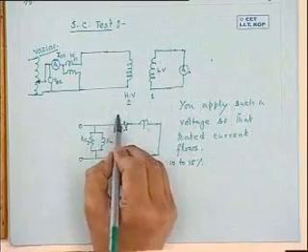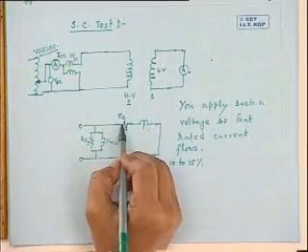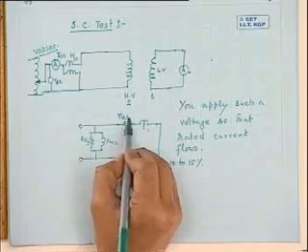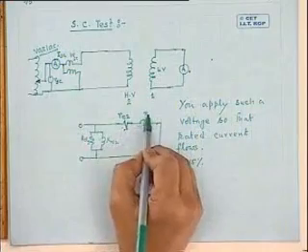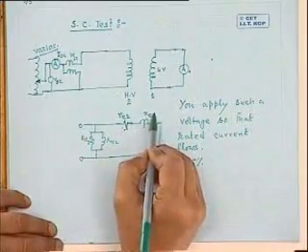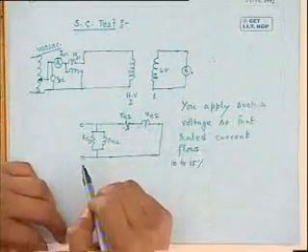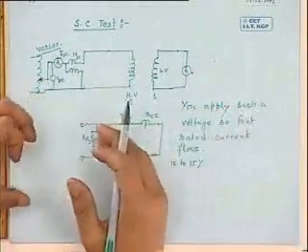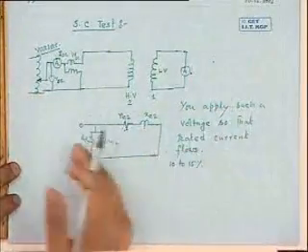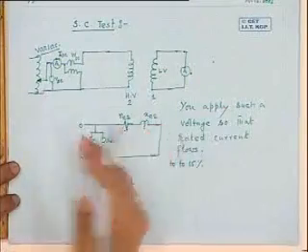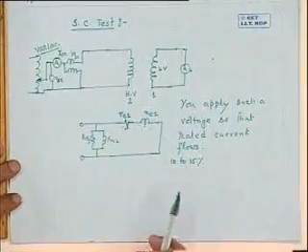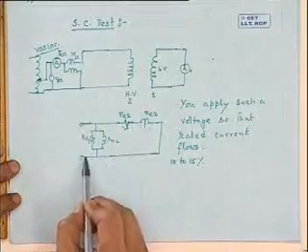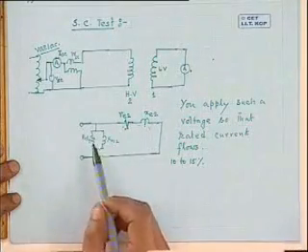And what should I write here? This resistance, what should I write? R equivalent, secondary side, X equivalent, secondary side. All impedances transferred to the high voltage side, I mean this side where I have applied voltage. Now here one important thing should be noted.